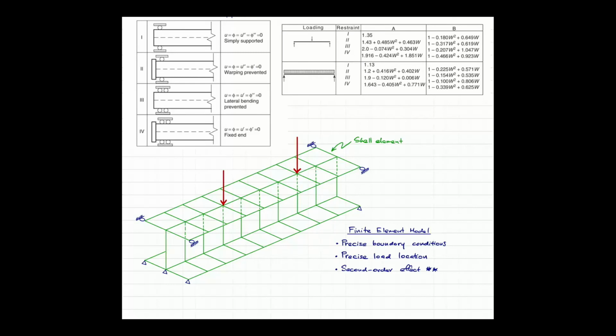Just the concrete alone in one beam, you cast concrete, maybe you need 2 mixes. So 2 mixes, you could end up with 2 different compressive strengths. Of course, you say that you measure everything well, you mix everything well, you do everything in the identical way, so you would suppose to get the identical compressive strength. But no, that never really happens for concrete.